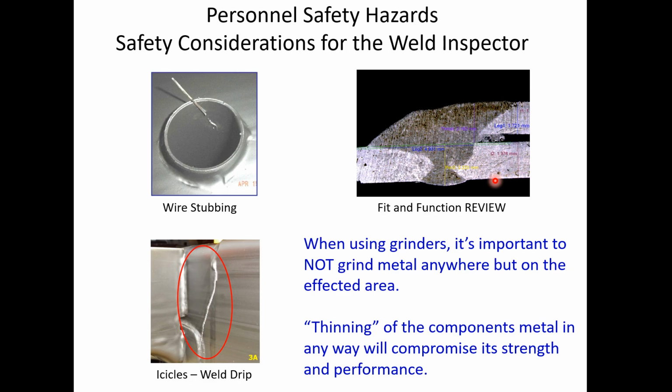Do not wait for some quality bulletin to show up and put this up on the board because it made it to the plant. If you see you're getting a lot of this melt through, that condition can cause some pretty serious problems. Sometimes there's allowances, sometimes there's not. You'd have to go to your OEM spec to understand this. But remember, it's not just a spec, it's fit and function, that's part of it. We need your attention on that.